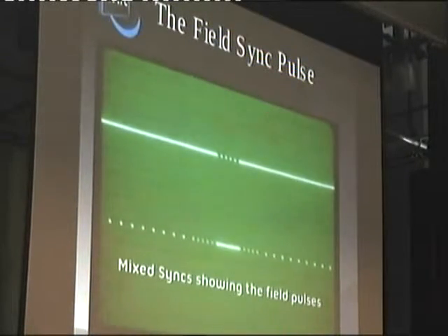And when I was at BBC Evesham, they made us do all sorts of calculations on this, and it really does work. But modern sync separators work on a slightly different principle. They actually count the lines. So instead of waiting for a broad pulse, they know it's 625 lines, and they're counting from the last one, and they're going 311, 312, now. And I say 312 and a half because, of course, that's what your number of lines in a field.